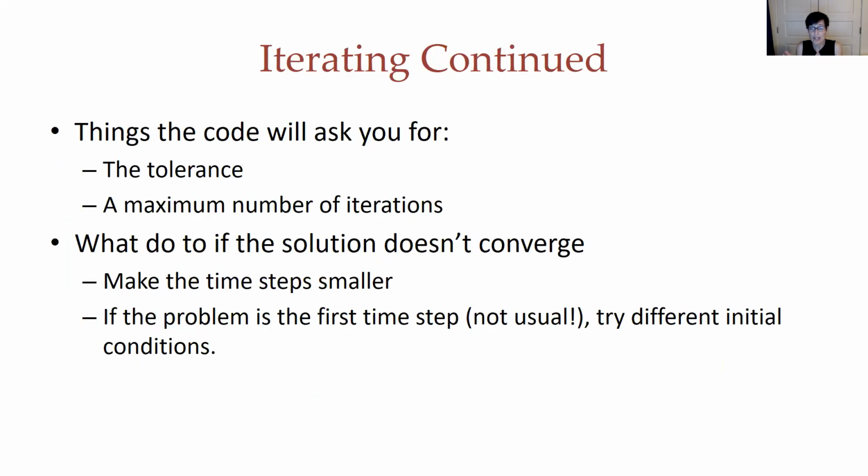It's like running each time step 100 times. And often, in my experience with groundwater codes, if it doesn't converge within about 20 iterations, it's not really going to. It's alternating between peaks or something in the solution. So my default maximum number of iterations is 20.